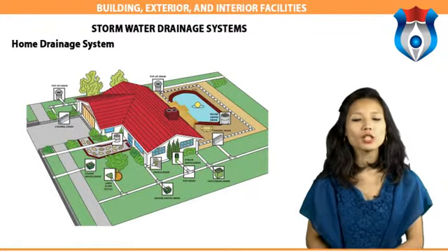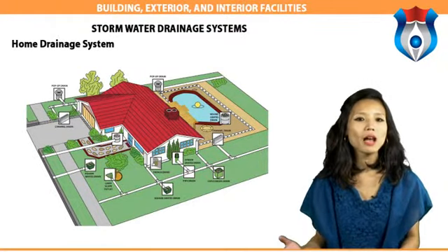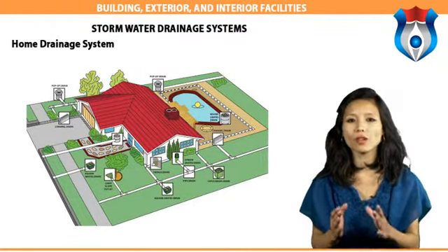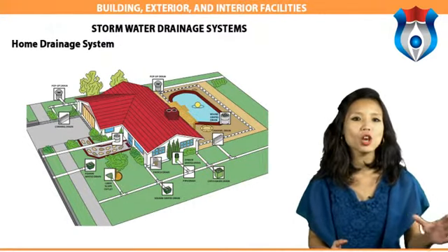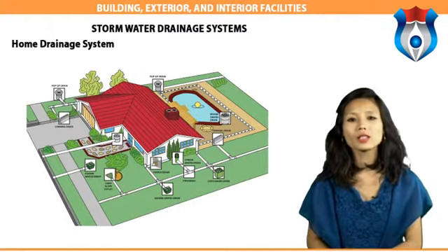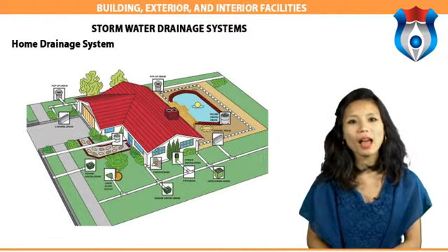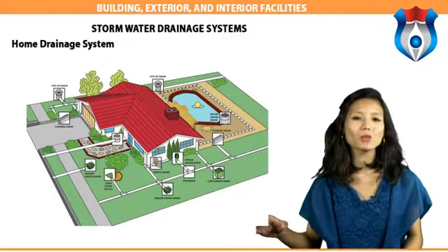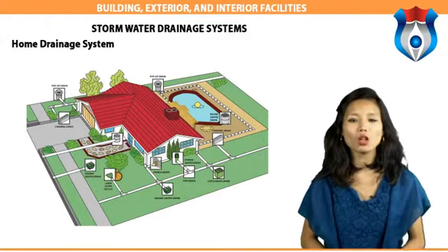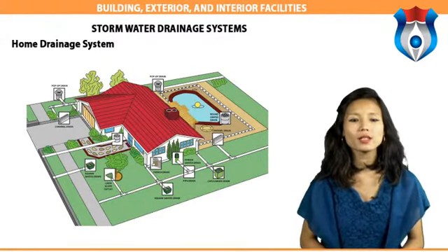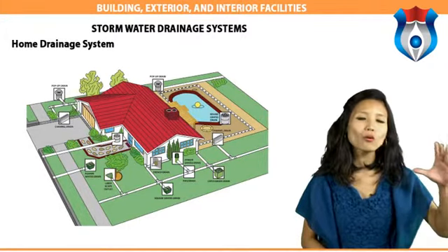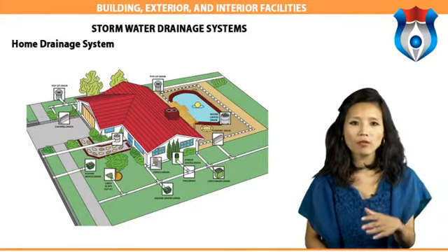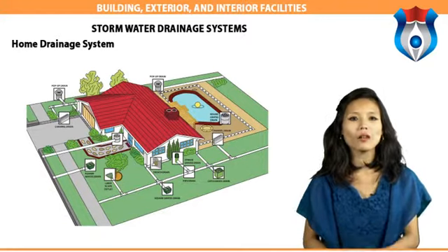Home drainage system. The sanitary line deals with all water disposed of inside the home. Water from showers, toilets, sinks, dishwashers, clothes washers and floor drains is channeled to a line on the basement floor. This line is connected to a larger sanitary sewer pipe located under the street. The storm water service manages roof and surface water that comes from rainfall, snow melt or garden hose.